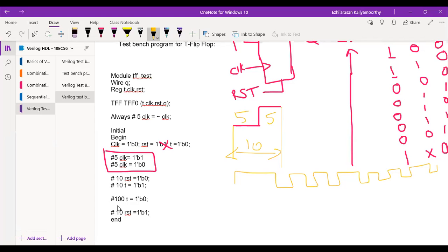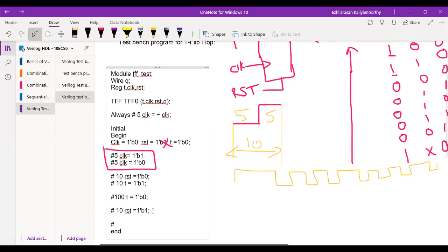So now I need to stop that. How can I stop it? One simple idea is there in Verilog. What I will do is give #100 and then $finish, which is one of the special functions in Verilog. If I give it like this, automatically what will happen? What is the simulation time from this? Any idea? What is the simulation time now?